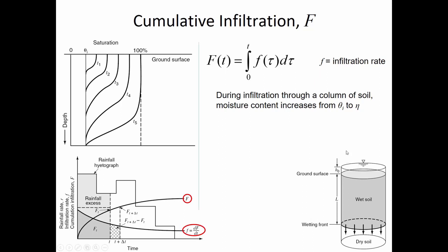Essentially what we're seeing is a column of water penetrating down through the soil, and there's this immediate increase from the initial moisture condition to full saturation, where L is going to be, over time, the length that that water column penetrates down into the soil. So we could know the cumulative infiltration amount by looking at how much of the pores filled up. The volume of water that was absorbed is going to be the overall porosity minus the initial moisture content. That's like a storage fraction, remember. So it went from the initial moisture content to fully saturated, when the water penetrates all the way down, so the porosity is totally full with water.